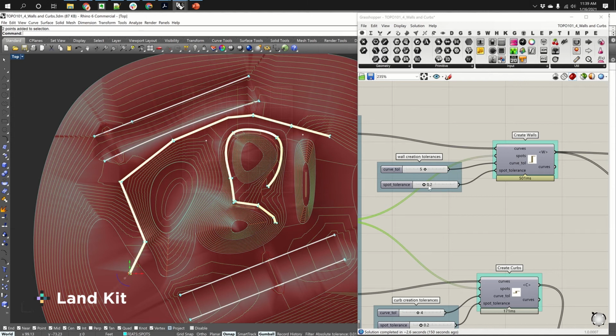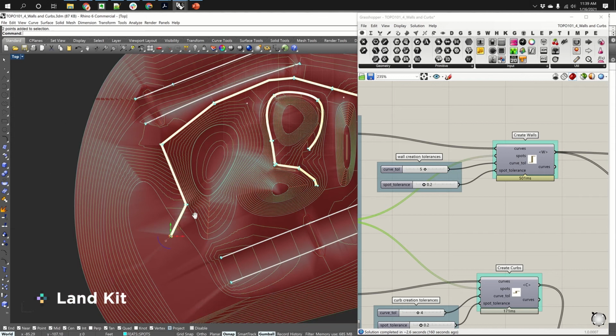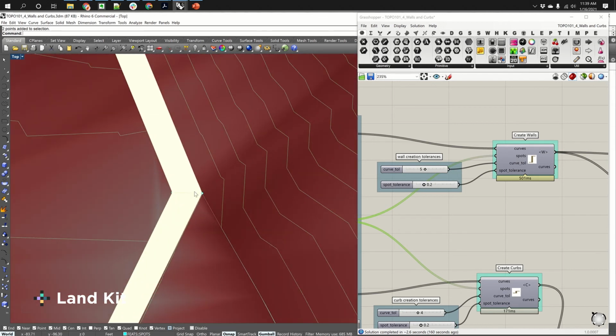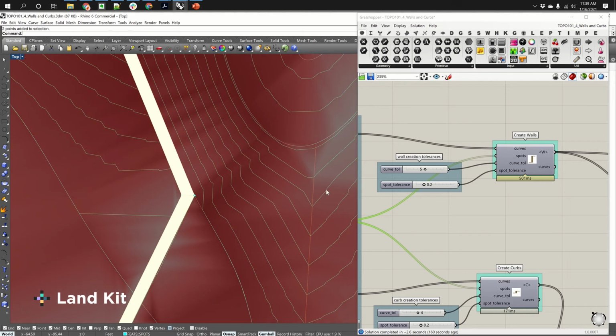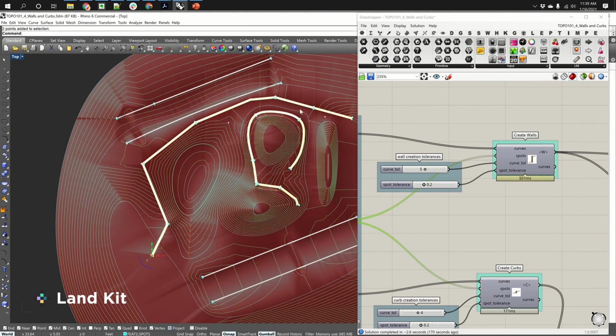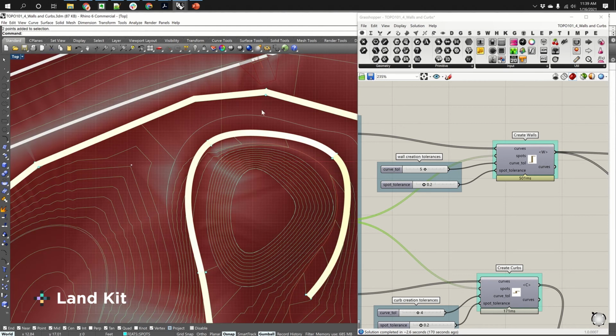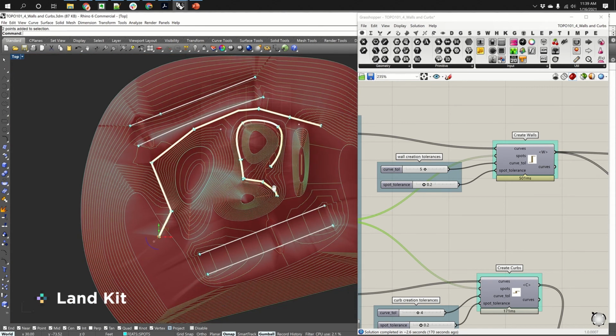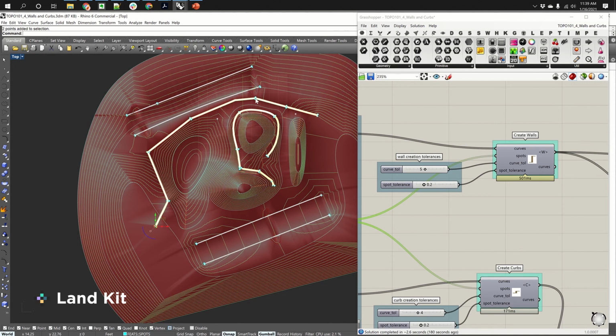Next, the spot tolerance, which is a bit smaller, is going to be used to associate the spot with the particular set of wall curves. This could be a bit higher since we don't have any walls that are really close to one another. We could almost have 1 or 2 feet for spot tolerance, as long as we kept those spots fairly close.